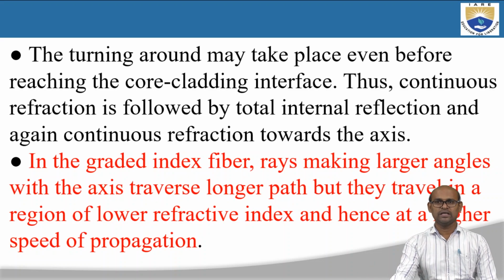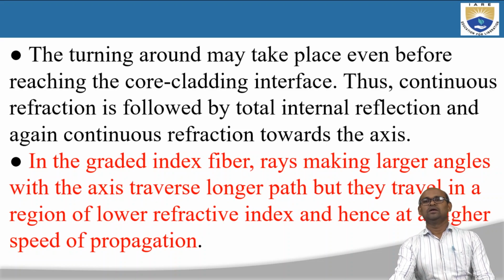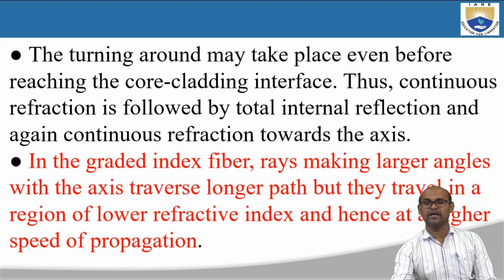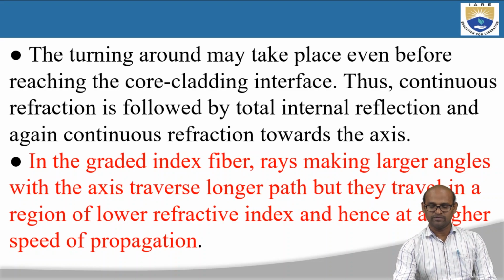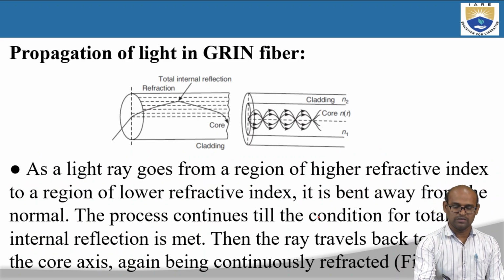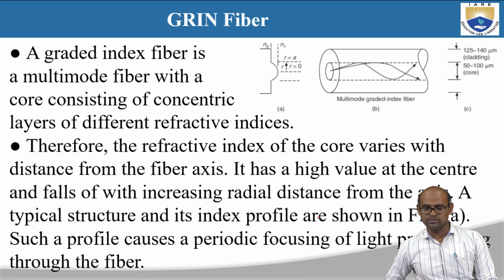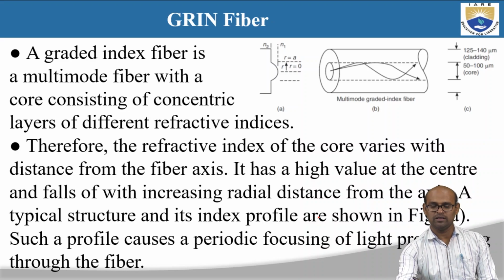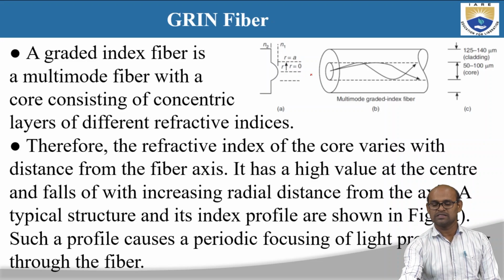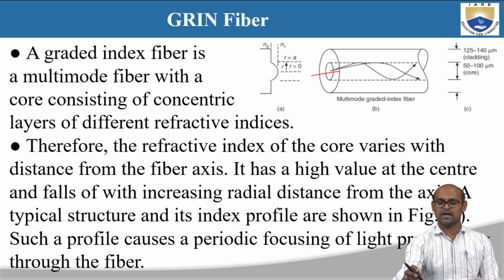Now coming to the graded index multi-mode fiber, it has an advantage now that you have a graded index profile. In the graded index optical fiber, the refractive index is not constant in the core, right? So let me draw this. So, yeah, this is the graded index optical fiber profile. So in the core, the refractive index is not constant. It is maximum in the center and it decreases toward the core cladding boundary.